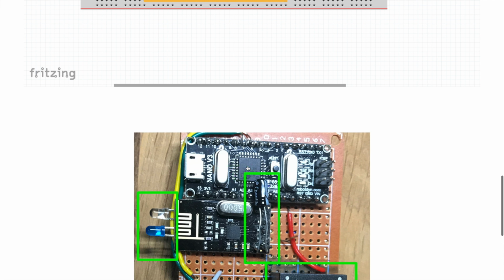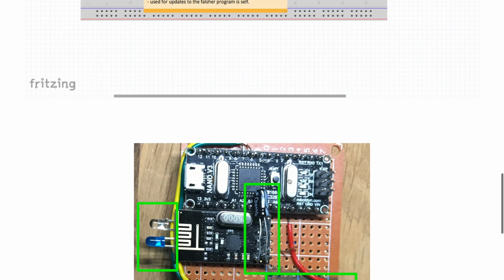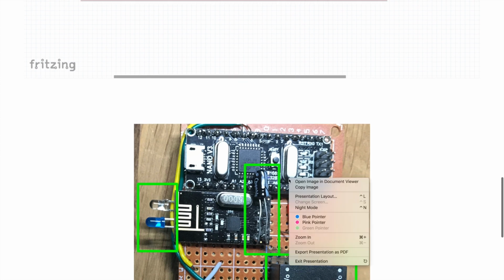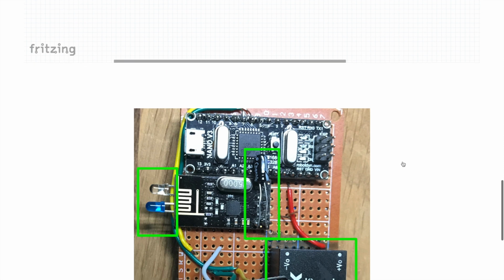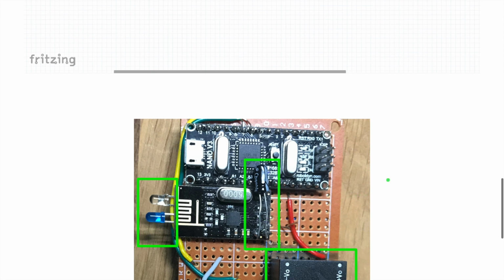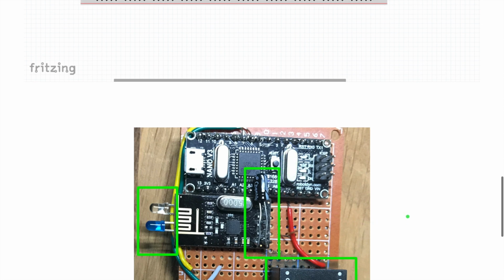So the thing that I did is to use the same nRF24 library, which is Mirf, the default one, and I tweaked it a little bit just so we'll have the same code. I will link it in the description as well, the code that I'm using, and I'm using it as a common project for everyone, and everyone is compiling with the same source and has the same commands. This way the registers are configured always the same way, and the bootloader and the sketch can use the same library for RF communication.